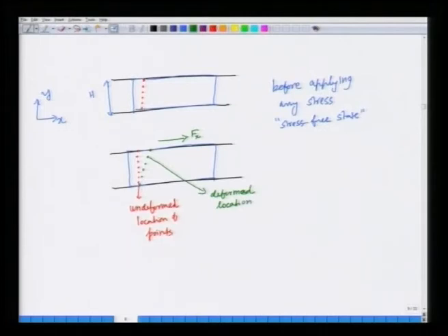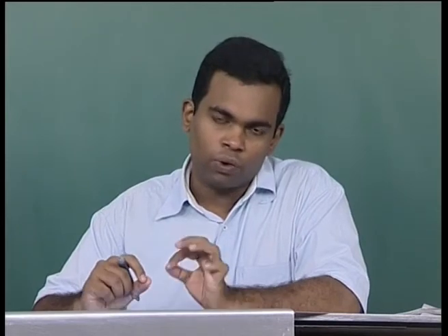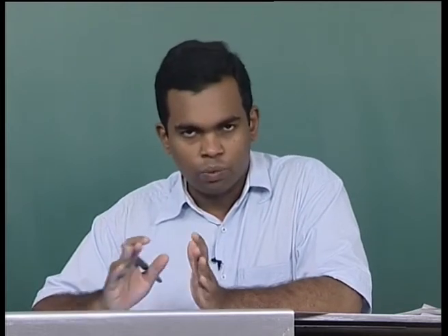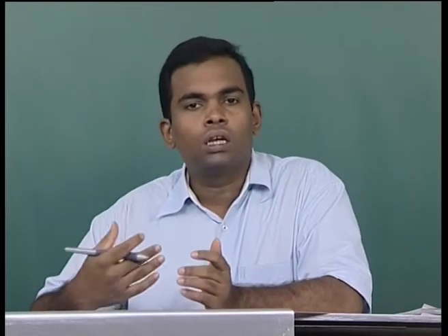We say that the solid responds to applied stresses by undergoing deformation. By deformation, we mean that various points that were there in the solid before the application of stresses will move to some other new point, but they will stop moving because once the solid starts deforming, internal stresses develop in the solid which will resist further deformation.